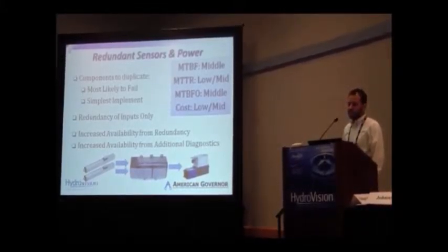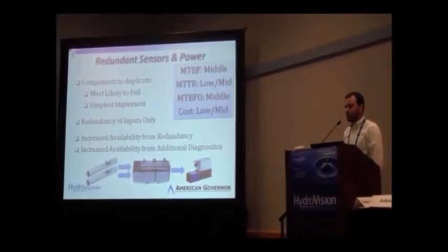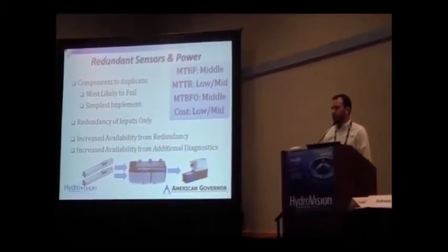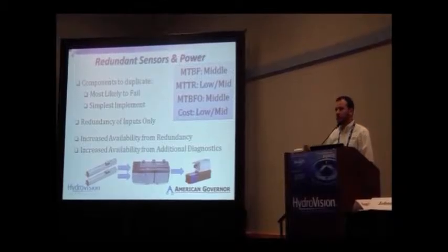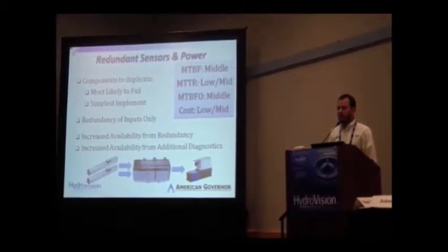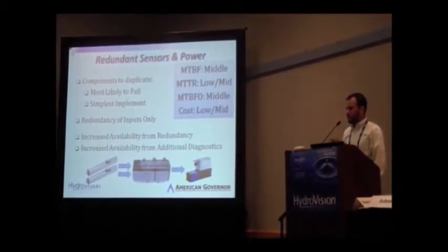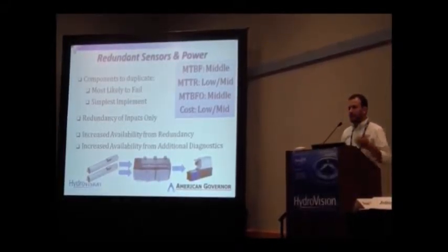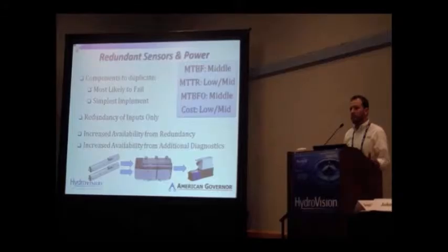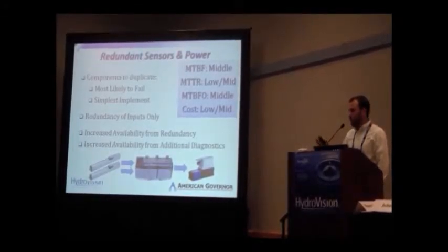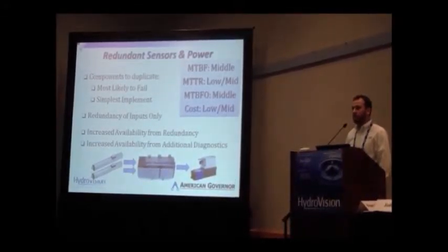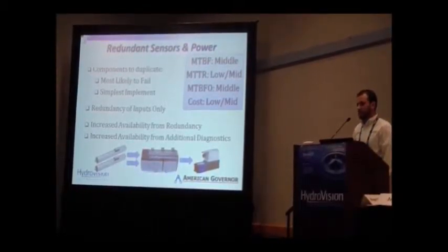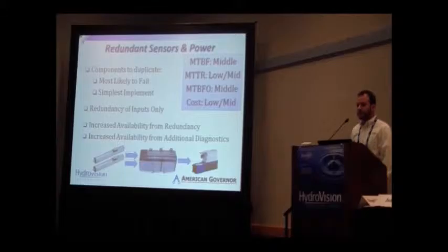And this is because you have increased availability from two sources. Obviously, your redundancy. If one power supply fails, swap over to the other one. You keep running. But also increased availability from additional diagnostics. If you have two pressure transducers and they disagree, you know you have a problem. If you only had one and it was off or was miscalibrated, you might not know you have a problem. So there's a whole another level of diagnostics and information that you gain just from simple redundancy.